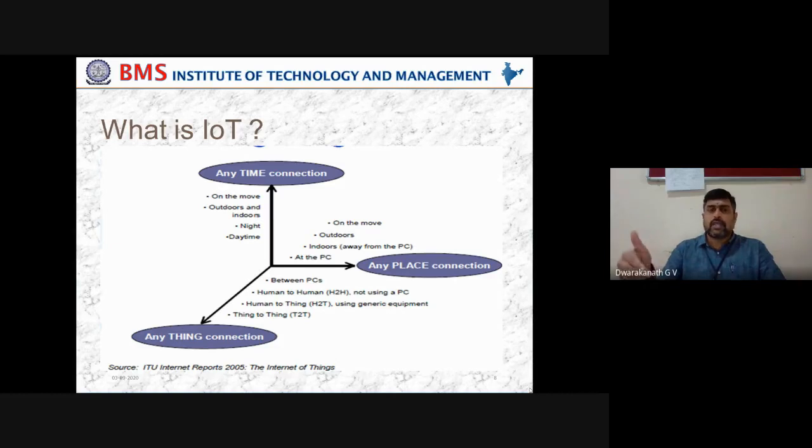Then what is the work here? That means your sensor should keep on sensing anytime. So what interval are you going to give to sense that particular situation? This is very much important. That will be purely based on your project. So here, every 5 minutes I will take readings of the sensor. It is left to you. Why? Because I am saying that if I check every 5 minutes, the moisture level doesn't differ within 5 minutes. This is my assumption. So in this particular concept, I will fix it like that.